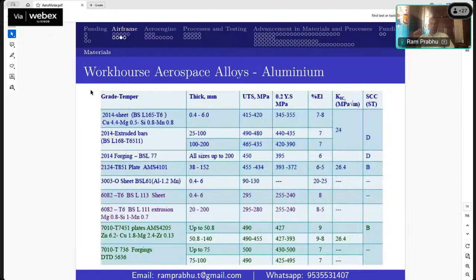Okay. So if you're a serious researcher on aluminum alloy, how to increase this upper bound limit, that is 552. Let's say you come up with a novel combination of composition of the alloy or novel manufacturing like 3D printing, use it. Bring the strength to higher than 550 MPa, minimum 6% elongation. Okay, at least 6 to 7%. If you're able to achieve that, it will get into the mainstream. That is the very good research you do.